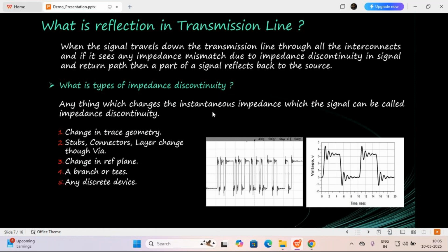As a signal integrity engineer, your job is to identify these places where ringing is present, and to provide the proper termination. You should provide the guideline to the design engineer on how to terminate the signal, so that there is minimum ringing. The ringing cannot be completely removed. It will be present, but it should be within the threshold limit.